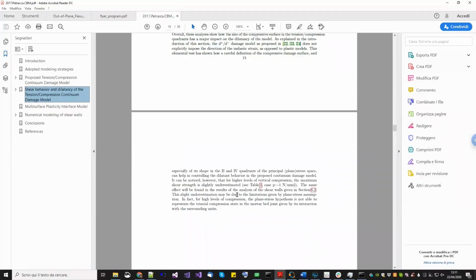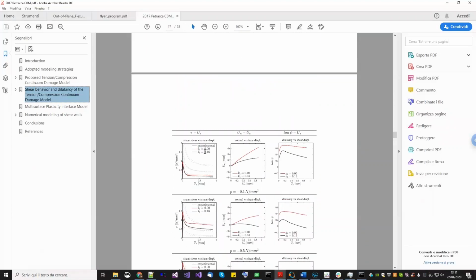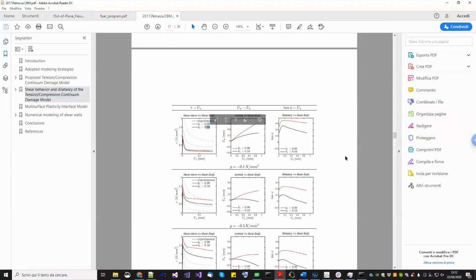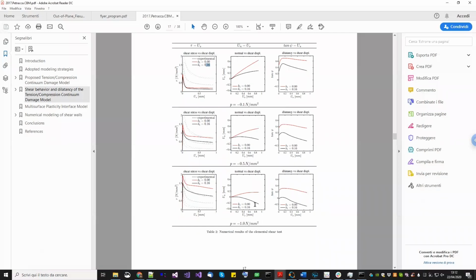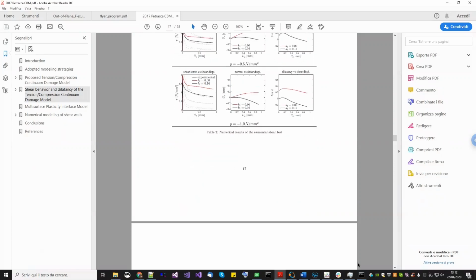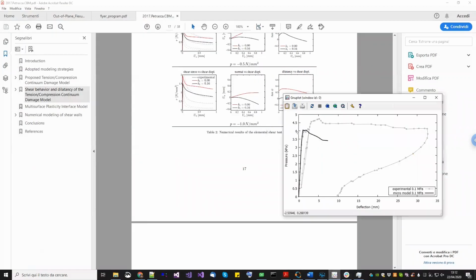And then I did some tests changing that parameter and trying to calibrate this vertical reaction. So for example, here I was trying with the minimum value and then the value of 0.16 that was fine in this example. In the example of the paper, of course. In my example here, it was 0.5, the good value, okay? So the problem is that you just need to do some calibration for this parameter and you need some experimental test that you can compare to, okay? Okay, this is fine, it's done. The curve should be underestimating the experimental results, okay?